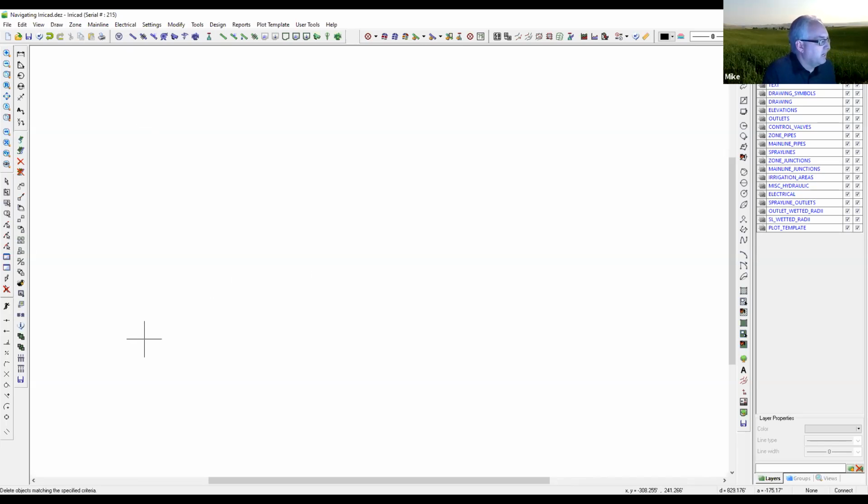So the way Irricad works is a little bit different than maybe some of the others, and that's that you have to use the Alt key to activate a keyboard command for the most part. So if you look closely across the top here at these menus, I'm going to hit the Alt key. When I hit the Alt key, you're going to see that there is a letter under each of those that has been underlined. In the case of the View menu, the V has been underlined.